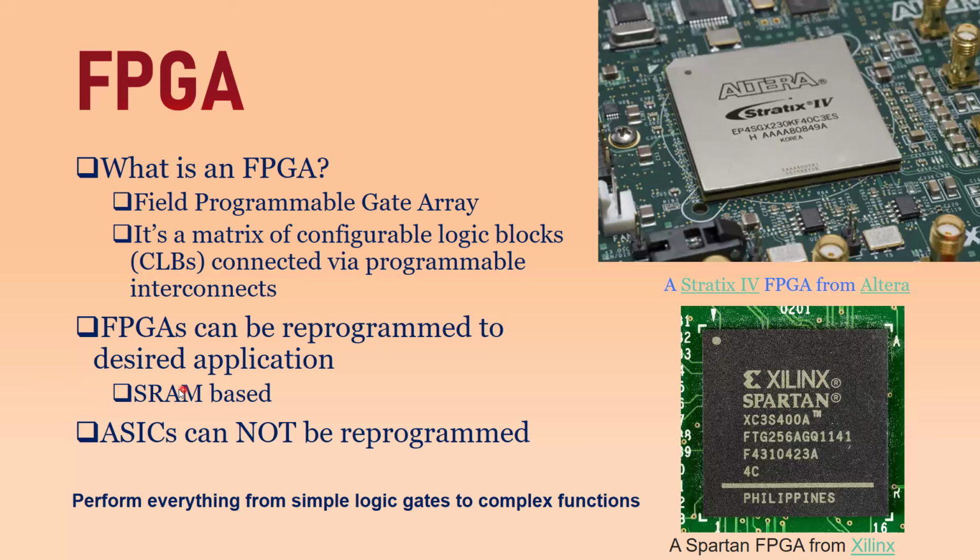Basically, most of the FPGAs are SRAM based. This stands for static random access memory. So you can actually erase it and reconfigure it with some other application. You realize one function in it and then you erase it. You can then reprogram it to realize another function. This is the speciality of this IC. You can say that this is a blank IC, and up to your wish, depending on your requirements, you can program it to achieve your target application.